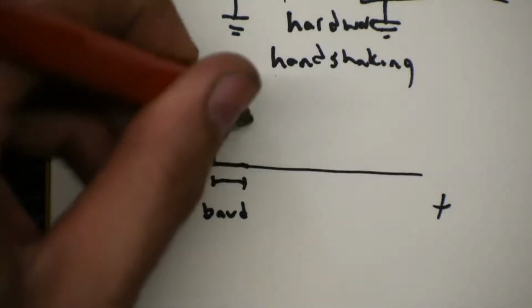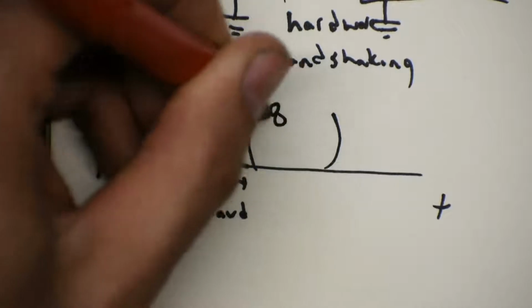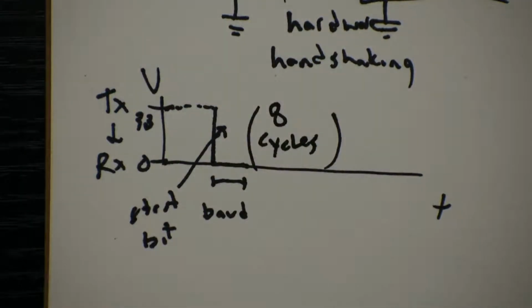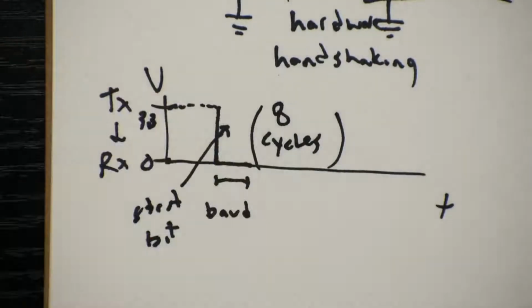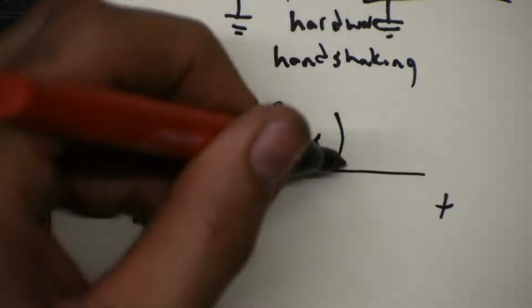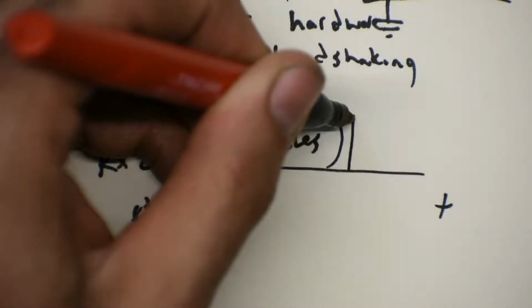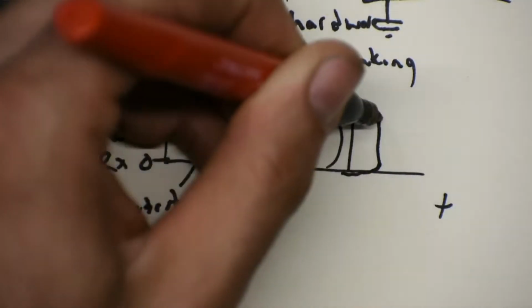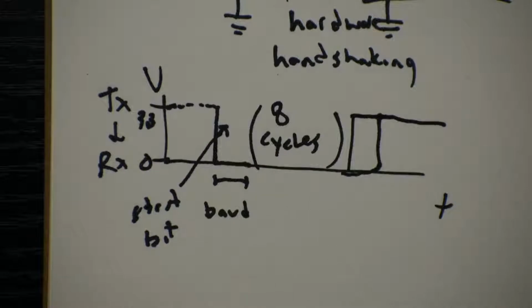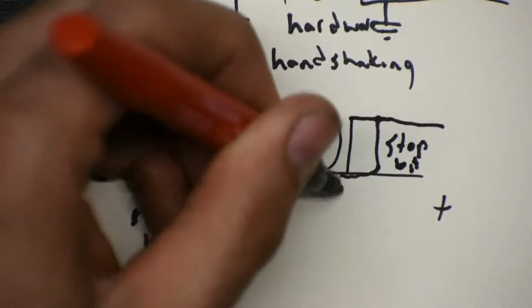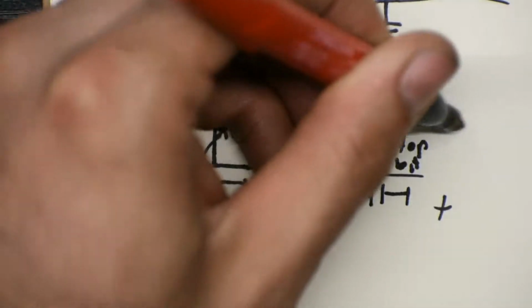Now for 8 baud cycles, the byte that you're sending, so the letter in ASCII that you're printing, gets sent. So 8 more baud cycles, you get 8 ones and zeros. Then when we're done, we get a parity bit, and then we get a stop bit. So that's a baud cycle, that's a baud cycle, and then we idle high from then on.